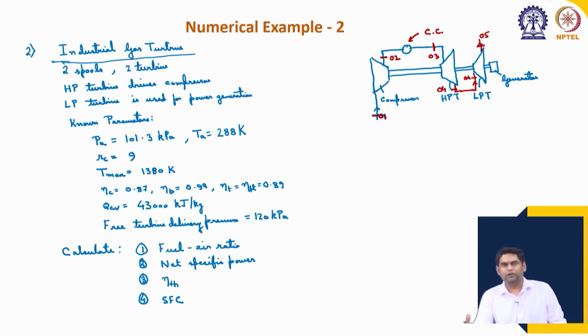They need not rotate at different speeds, but later we will see that because the low pressure turbine is much larger than the high pressure turbine, it needs to rotate at a lower speed. So, the advantage of a two spool turbine is that we can design a gas turbine system with a significantly larger low pressure turbine without dividing this gas into two different turbines.